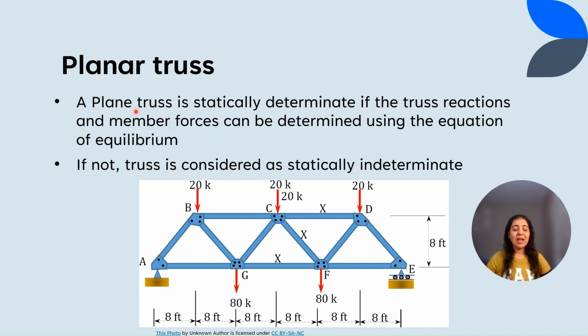A plane truss is statically determinate if the truss reactions and member forces can be determined using equations of equilibrium. If not, then the truss is considered statically indeterminate. We already saw the equations to determine whether the truss is determinate or indeterminate.